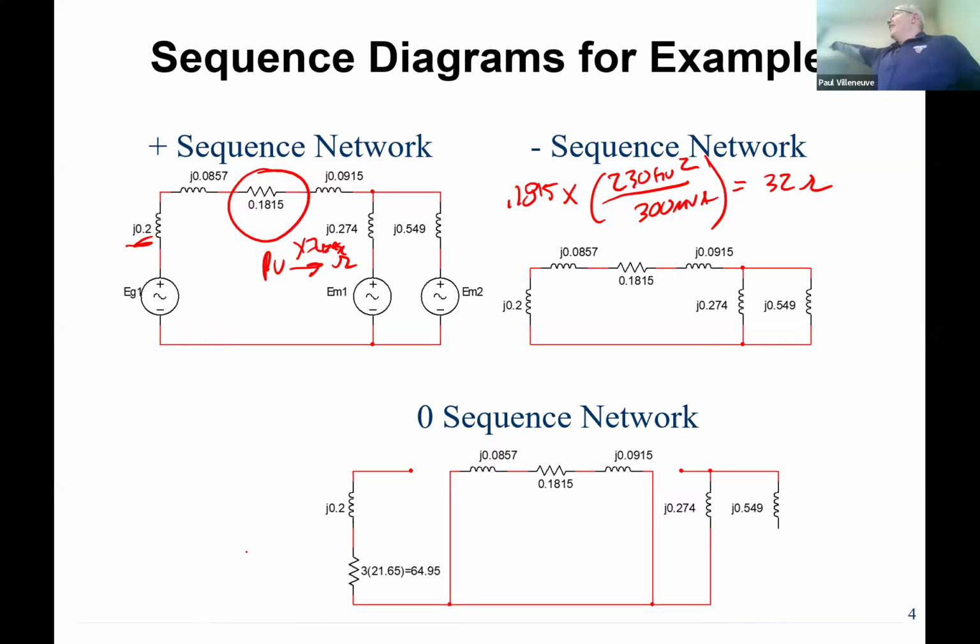If I buy a generator whose voltages are 13.2 at an angle of 0, 12.5 at an angle of -10, and 12.7 at an angle of positive 125, do I have a balanced system? Plugging that generator in and turning it on with all my loads, I'm going to get neutral currents flowing, and my voltages are going to be different amongst phases. My motors will spin at weird speeds, or vibrate a lot, because sometimes I have a lot of magnetic field exposure and sometimes little. That would be a complete disaster.